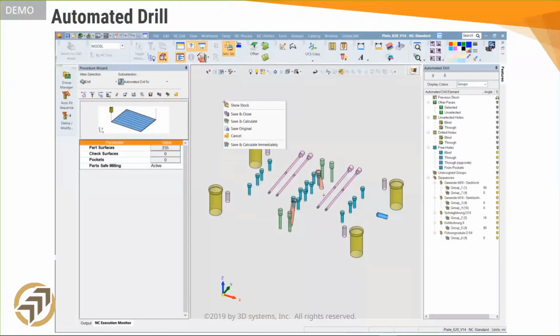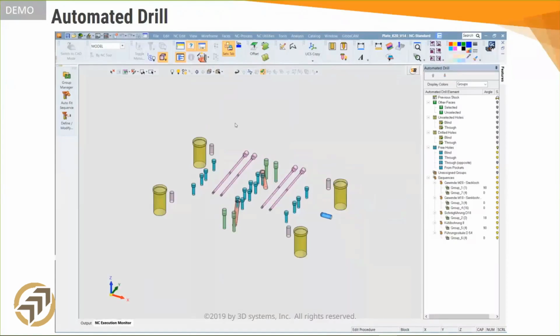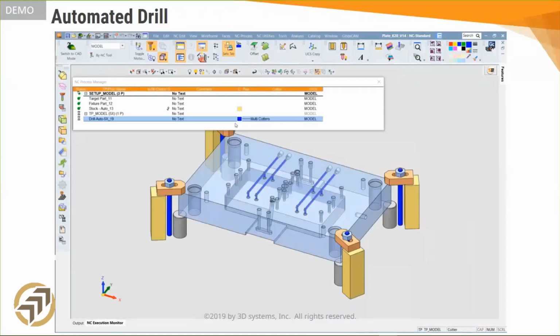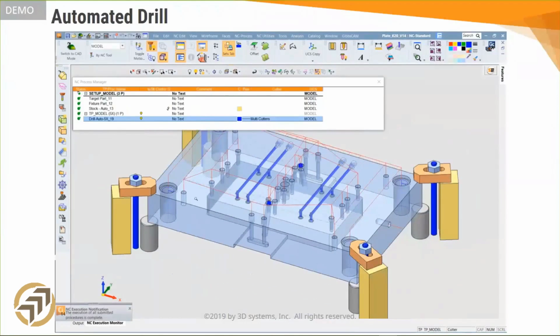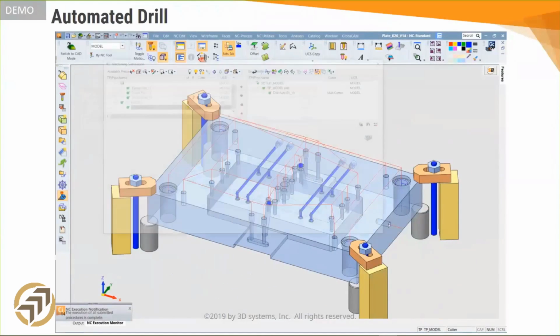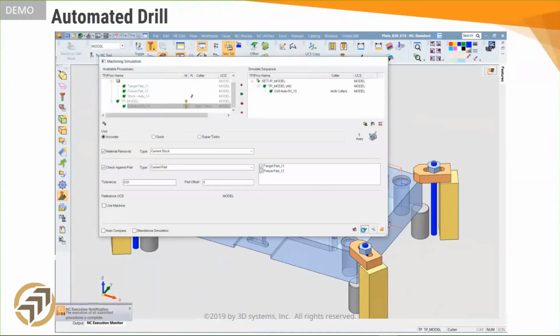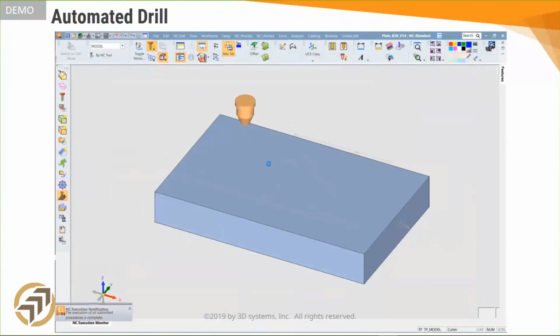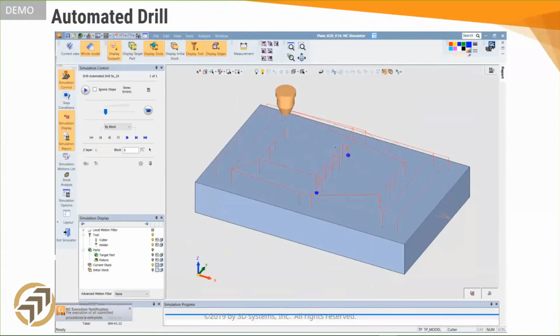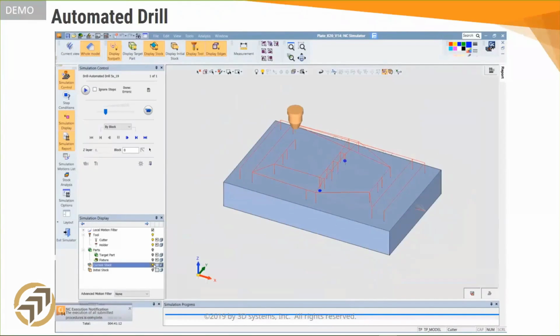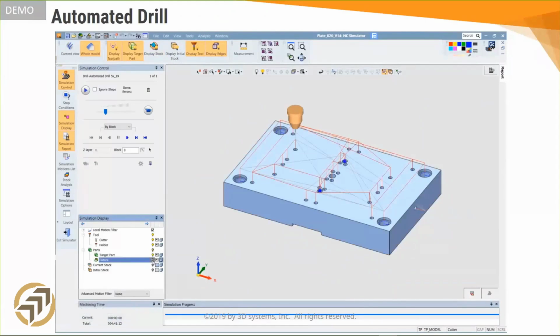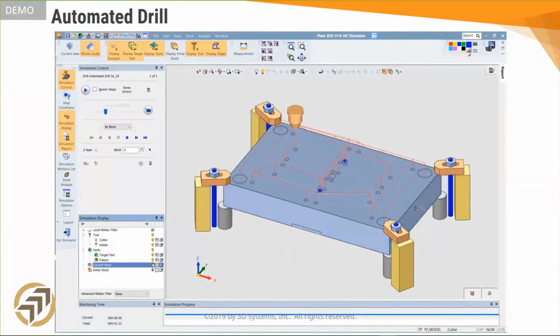The different hole groups are color-coded so that you can easily examine them. The saved drill sequences that are applied to these groups include the order of tools that are needed and the type of drill commands that each one uses. And the whole geometry itself provides the drilling start points, end points, and even gun drilling and breach techniques. The resulting toolpath will be optimized to minimize tool changes, yet keep the drilling logic of each hole as required. The toolpath considers the stock, it prevents shank and holder collision, and it even suggests the minimal clear length to the drilling tools.